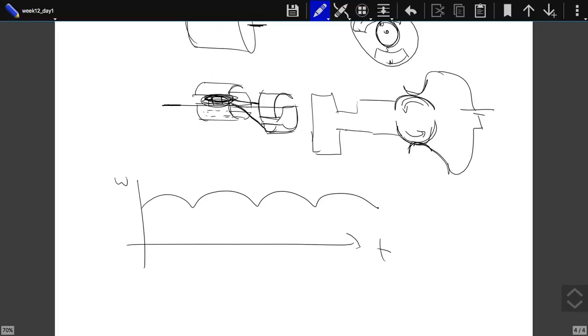That's another alternative. You can just connect it to an AC supply. But in that case, the thing you have to pay attention to is that there is a phase of AC, and there is a phase of the rotation of your motor. They have to be in phase. AC will be changing its direction of the current at a fixed number of times. Your motor should be catching up. You have to make sure that it is catching up. If they go out of phase, you might end up with your motor rotating in one sense at some time and then just flipping directions. It can be chaotic.